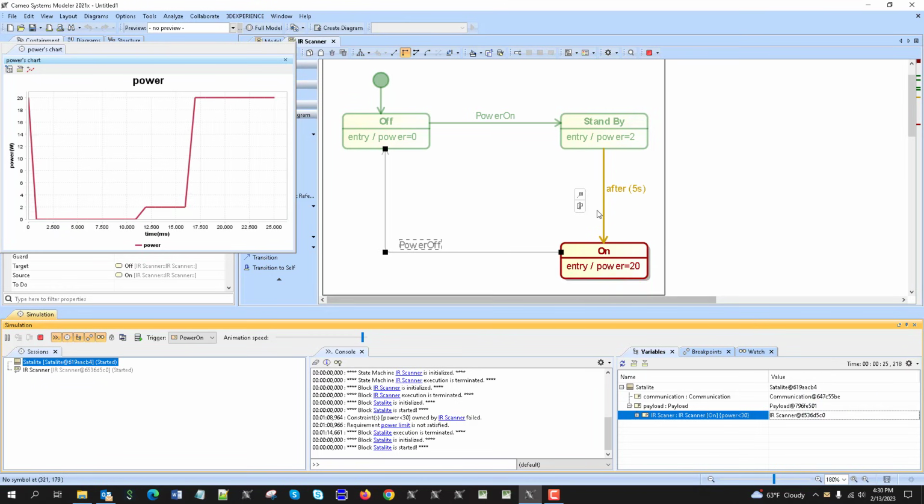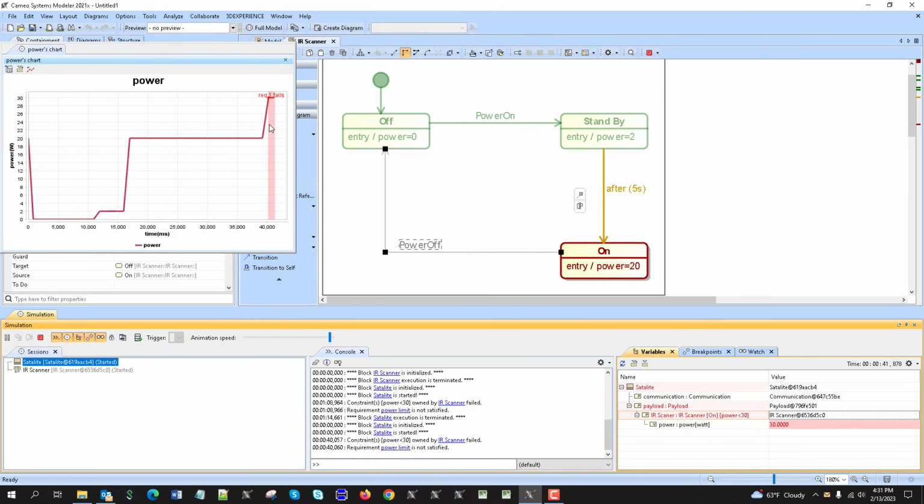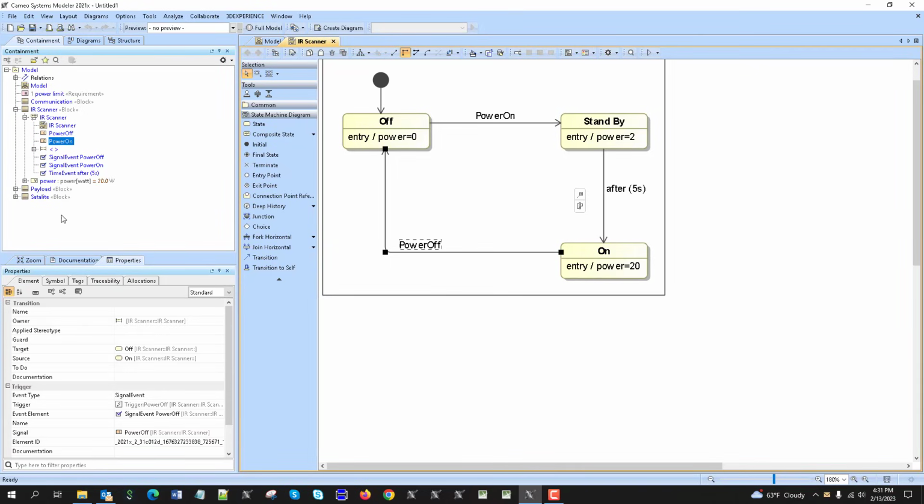As you can see, the default time is milliseconds. So it's not very convenient for us because we want it to be in seconds. We have the smallest granularity of time as 2 seconds here actually. I just wanted to show that if we increase the time here, we can see that the requirement also failed here. See? We can actually control that through simulation config.